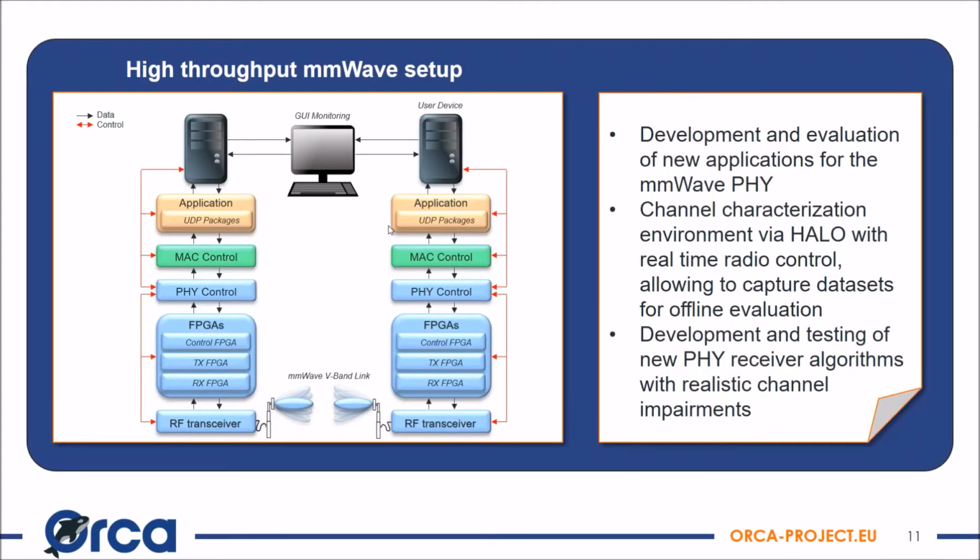In the last offer of this OpenCall for the experiment, we introduce a millimeter wave system. The system is composed of an access point and a user device, which are equipped with the NI-PXI system. Each device has a 60 GHz steerable antenna attached to it, and it has a list of predefined beams.